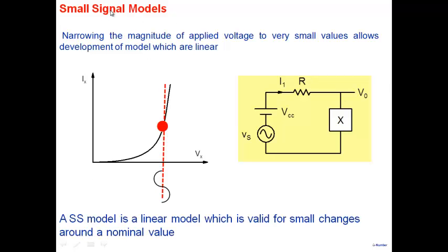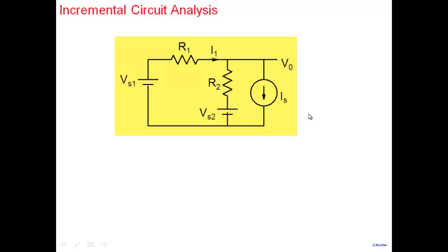And the reason why we build this small signal model, you'll see, is that my device is nonlinear. And the small signal model that I built, because it is small, is linear. And I told you that you obtain simplicity often by linearizing. Linear models are simple. Nonlinear models are complicated, right? So small signal models are an outcome of linearizing a device, linearizing the mathematical equation, and obtaining it. So let's discuss this in a little bit more detail.